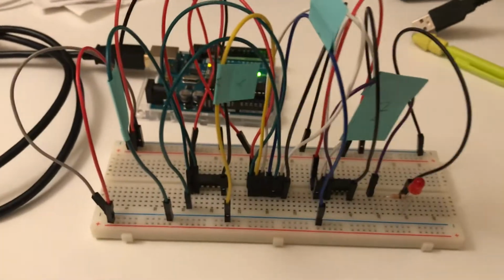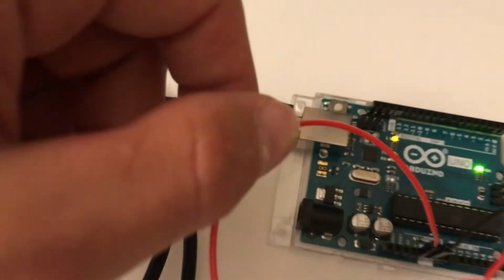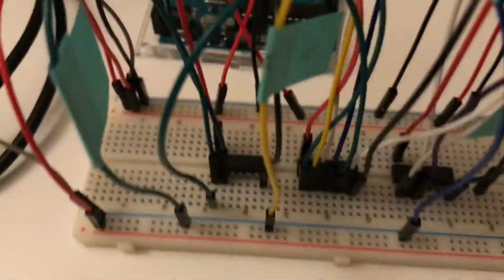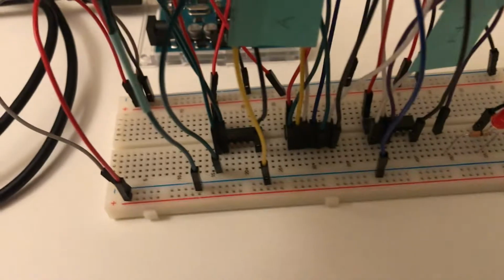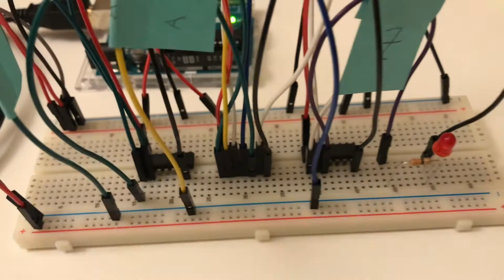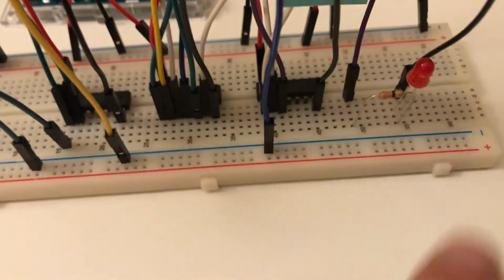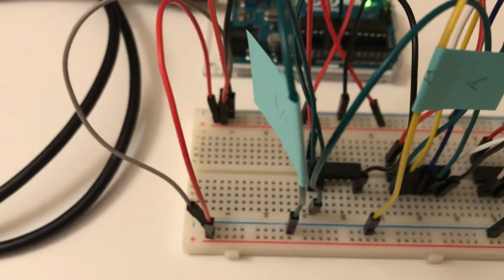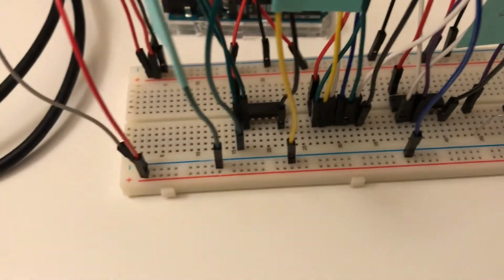Okay guys, now I have my circuit wired up. You can see I have my red is in power, black is in ground. Same thing here. I have my selector. I have A as yellow, B as blue, and then Z, I just labeled as the output, which we're running through the 330 ohm resistor, through the LED, which is then grounded. We have the NOT gate, the AND gates, and the OR gate in this chip.